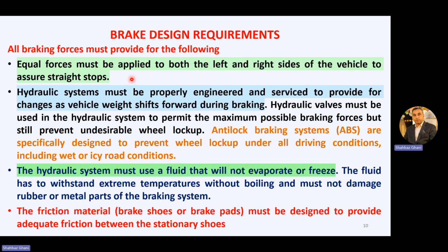Suppose you design a brake, but it is not applying equally on the left and right side. If it is applying more on the left side and less on the right side, your vehicle will pull to the left side, or you may topple the vehicle. So equal force must be applied to both the left and right side of the vehicle to assure a straight stop.